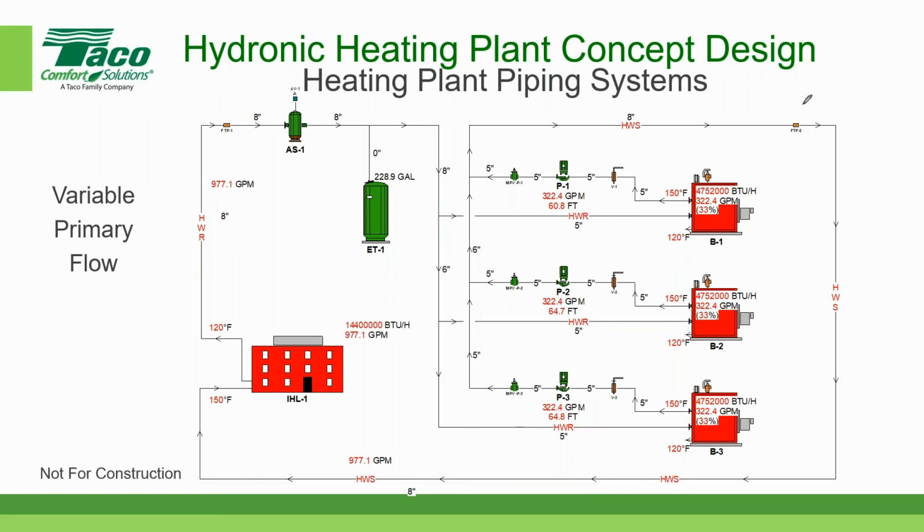That's correct. So in other words, this boiler right here, let's say I'll just circle it. This little guy right here, if your load had dropped off in the building, as each one of these other boilers would shut off, you're running this boiler at 100% of its own capacity, which is 33% of the building demand. And now if you had a turn down ratio of 20%, 20% of 33% is around 6%. Does that make sense? Yep. Any other questions? No, proceed.